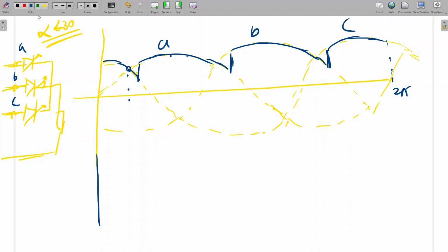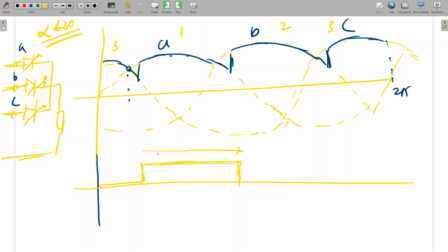So if you see the current, here 1 is conducting; A means 1, B means 2, C means 3. So what will the current waveform be? For A, this is the current waveform previously. Here to here, if there is no overlap, what is this angle? How much will this duration be? This is 120 degrees. Okay. So see, if overlapping happens, then what will happen?